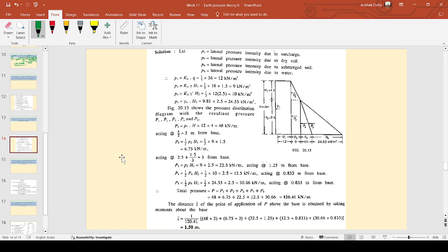Sir, here in this question, by default we have to assume there is no weep hole. Yes, no, you don't need to assume any weep hole. If a weep hole needs to be assumed, that means the water is discharging, right? That will be mentioned in the question. By default, if nothing is mentioned, you have to take the water submerged assumption. Every time if there is water mentioned, submerged unit weight plus the weight of water as a pressure intensity.